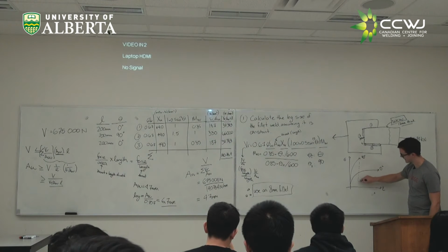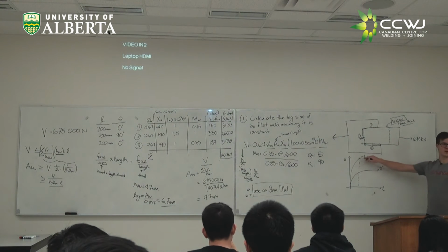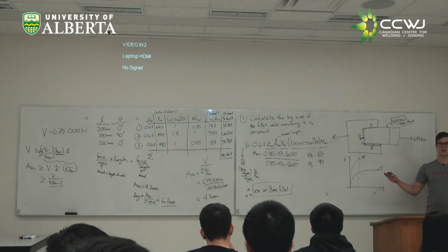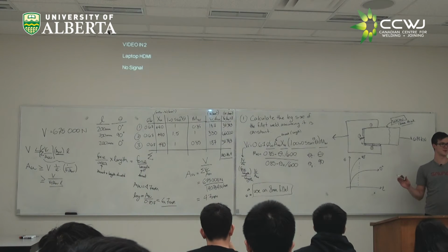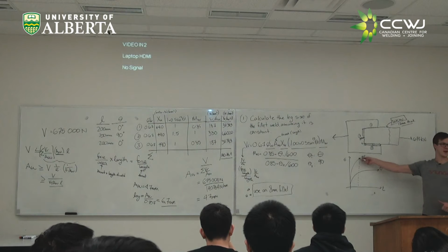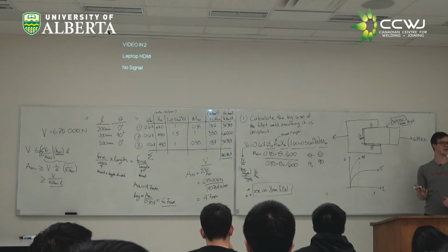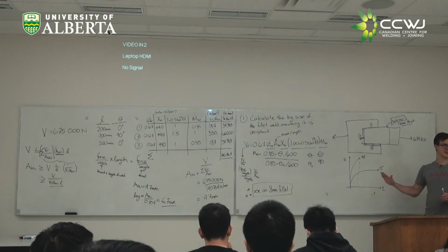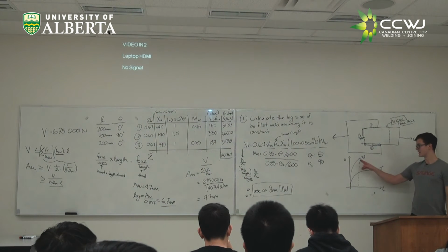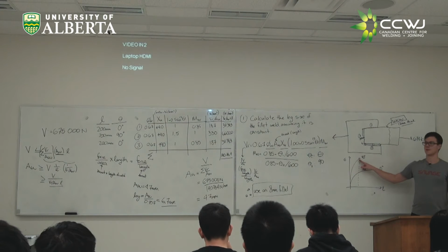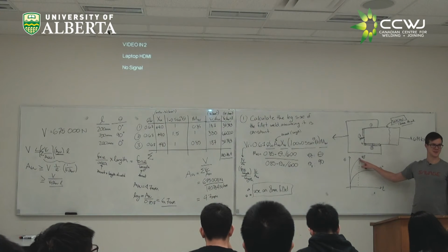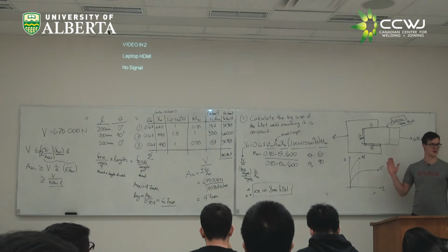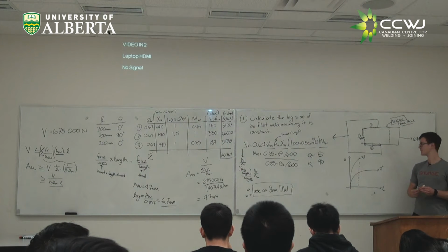And if we trace this down, at the point where this weld fails, that's where we say we've reached the design point of our structure. We're designing so that this never happens, so we never exceed the yield strength of our material. Depending on your experience in design, you might have come across situations where you start to design into the plastic region. That's something totally different. We're not going to worry about that. So when we exceed our yield strength, our ultimate tensile strength of our material, that's where we're calling the failure point, right?